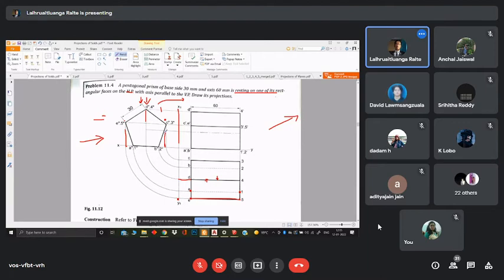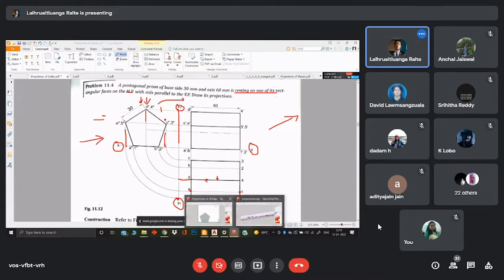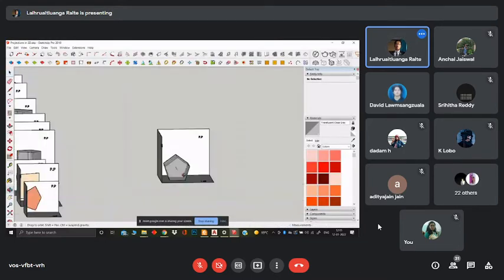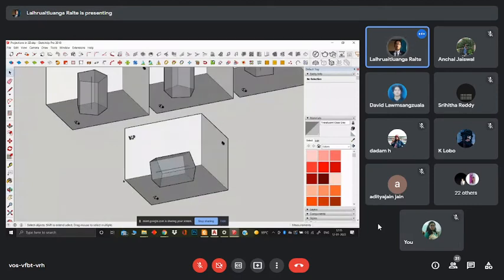Okay, any question? And before that, when we employ a profile plane, we have our reference line, XY line, as well as a reference line in aid of the profile plane. So, which is something like this. So it would be something like, if this is our XY line, reference line going, this still would be our X1, Y1 reference line. Okay.